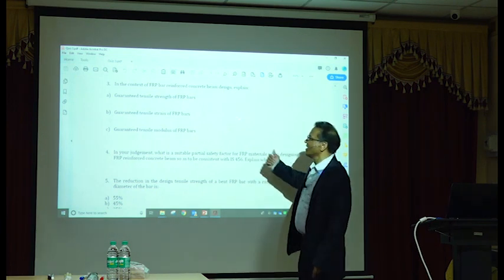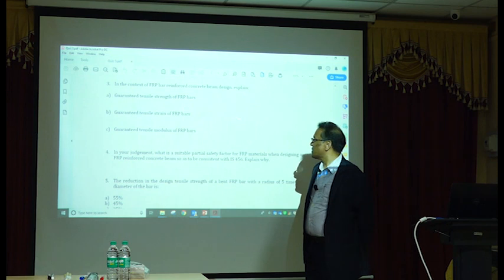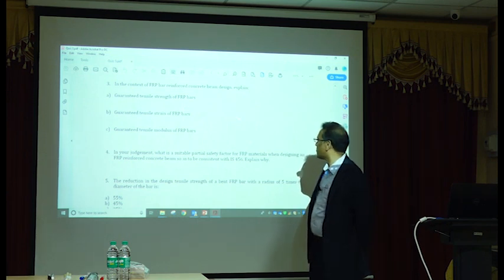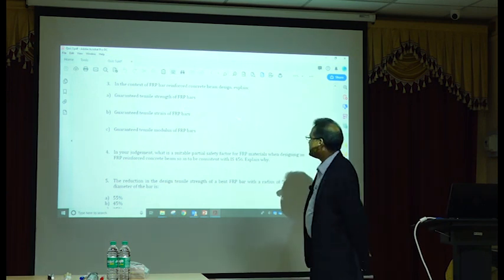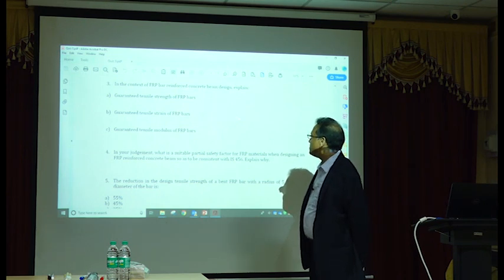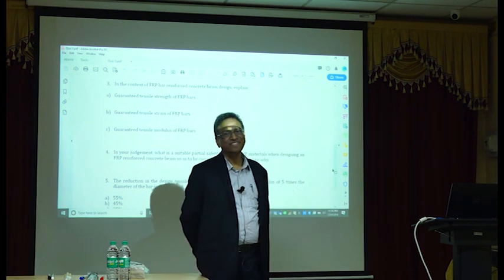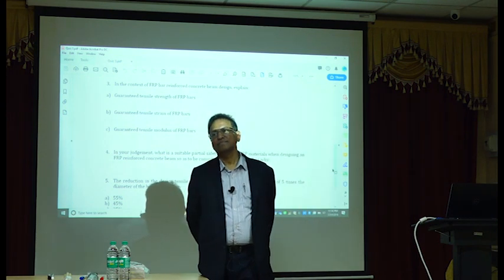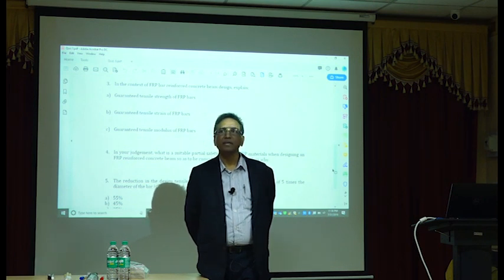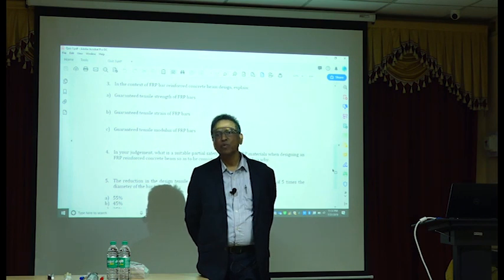So, in your judgment, what is a suitable partial safety factor for FRP materials when designing an FRP reinforced concrete beam so as to be consistent with IS 456? What do you think? Let's go back step by step. Steel is a very ductile material, right? So we use 1.15 and we accept it.